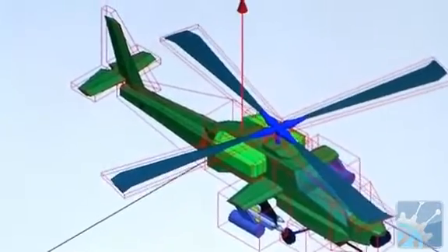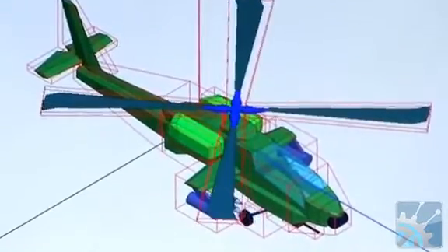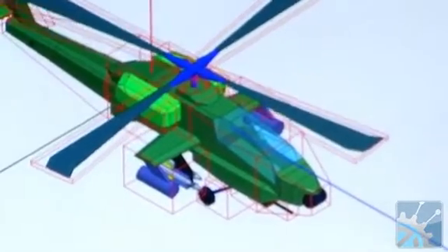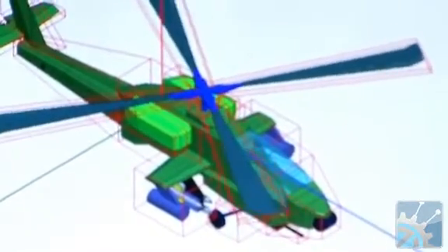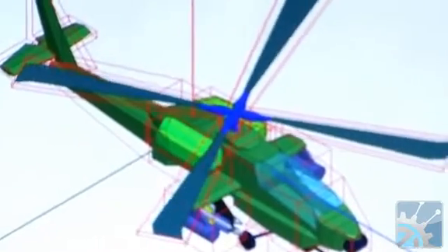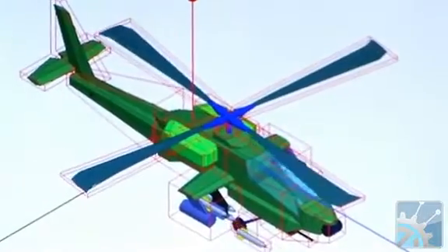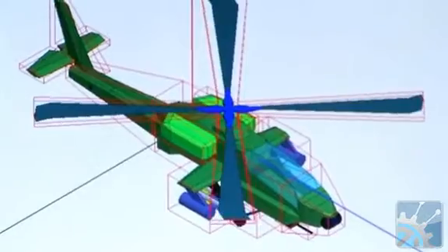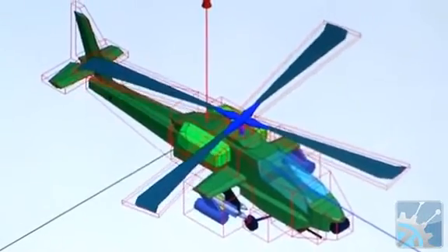And this is sort of new to people who have been using HFSS for years. You can have, in effect, with this box, a very conformal air volume that wraps right around the geometry. In fact, you can even have that conformal volume move with your geometry, as we're showing here. And to solve for the free space condition for this model, we use an integral equation or method of moments solution on the boundary of the air box, but still use the rigor and accuracy of finite elements interior. And again, use an iterative technique to resolve the solution between those two domains.